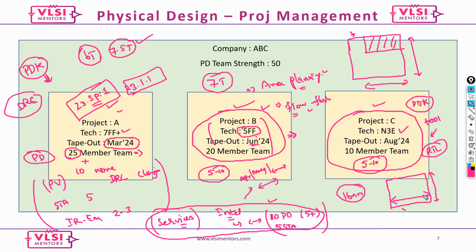And you may have IPs, for example macros, so you cannot place them randomly the way you used to do. You have to place them in certain locations, because otherwise you would have base DRC issues. When we say DRCs, we have base DRCs and